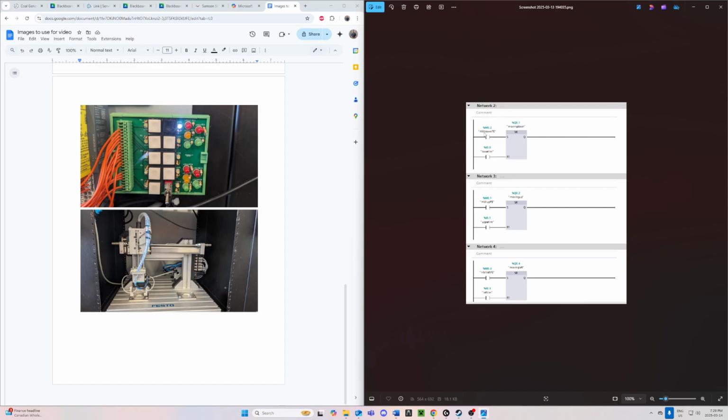So you will have these HMI, which is human machine interface, which is a screen that will be already set up for you, where when you push HMI down, it will set the moving down output command to 1, which will cause this robot arm to extend and move down. When it hits the lower limit, which is a sensor that is being applied onto the robot, that sensor acts as an input, like a button, and then sends that command to reset as a 1, turning that set to a 0, turning off moving down.